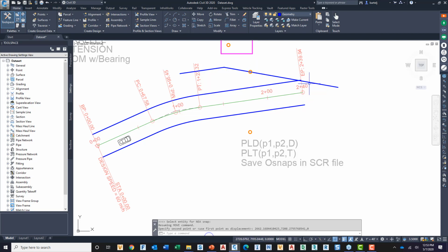Let's do something similar. I'd maybe like to put something at 75% of the length. I need to put a stripe or something in there that's 75% of the total length. I don't know what the length is, so I'm going to have the system figure that out for me. I'm going to say move this from the center of here. We're going to use another formula. We'll say apostrophe calculator.